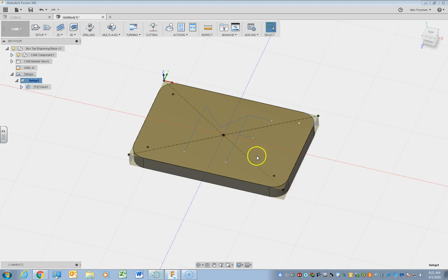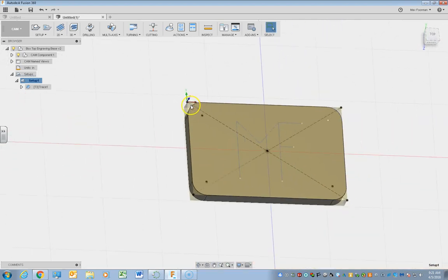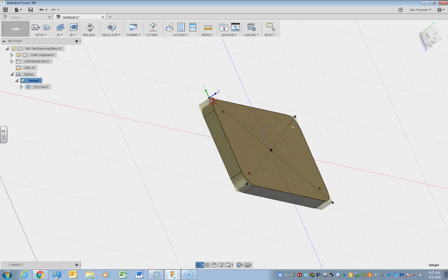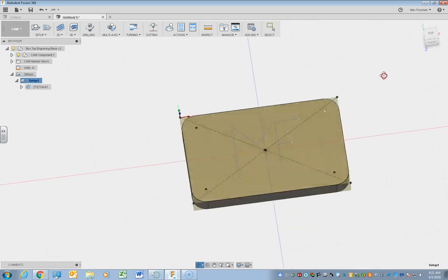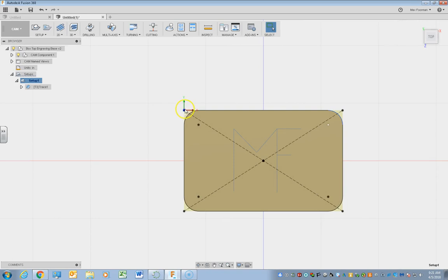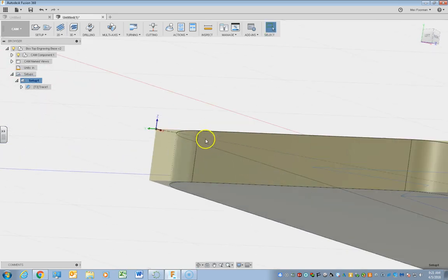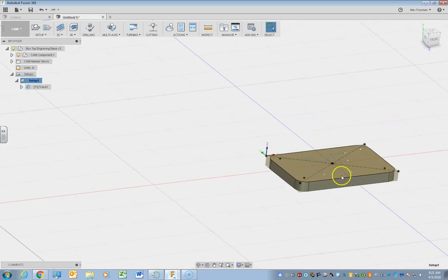Now, before you do that, we're going to have some people check off on you, but the main thing for you all to make sure that you have done when you did your CAM stuff here is making sure that that work coordinate system here is actually set to be in the upper left-hand corner of what would be your box top part here for this specific assignment. Okay, so there's the X and Y 0 point with your Z height here. If this is in any other position, you need to stop what you're doing, find some help, and reset that up correctly. Because if you post this out in the wrong place, we can have real big problems when we get out to the machine.